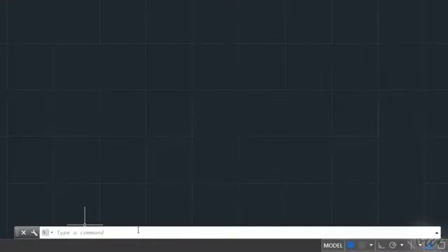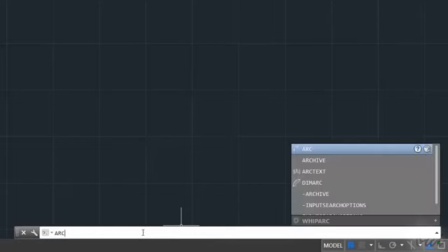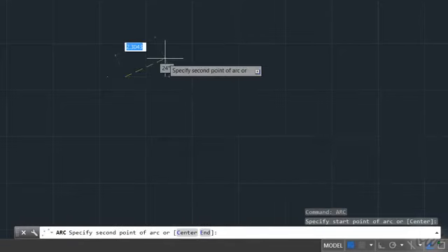While drawing a rectangle, you can choose Area to draw a rectangle with a fixed area. Very important is also the command line below. This is used to quickly enable any command by typing its name. For example, if you type Arc, a list of commands shows up with all the tools starting with Arc, such as Arc or Archive. Use the up and down arrow keys to browse for the right command and use the Enter key to choose one.